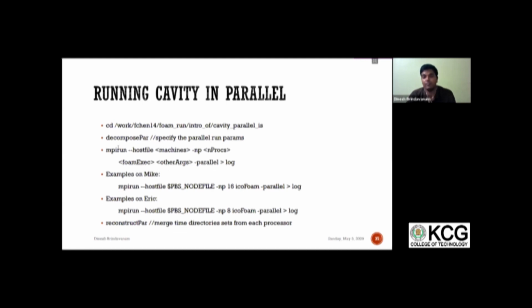These are for the Linux platform. There's some tweaking in the Windows version, for which you can go to CFD support, the website which I showed you for downloading. In that itself there is documentation. For example, if you are using a Linux based system, the command remains the same, mpirun, for running a multi-parallel simulation. Whereas if you are running on Windows, it is called mpiexec. So it is slightly different between the Linux version and Windows version.